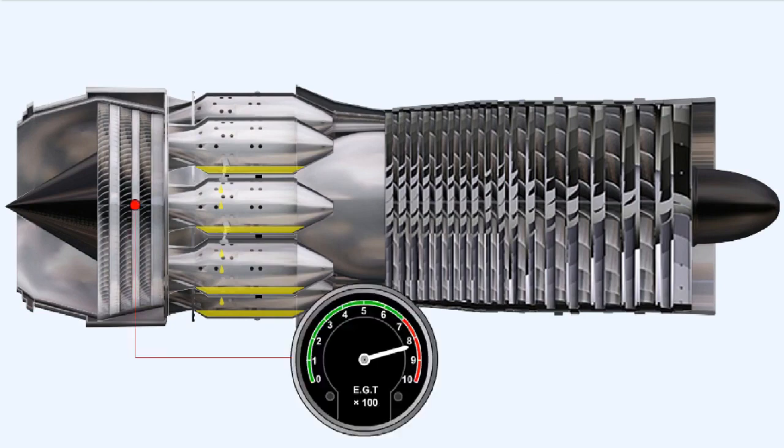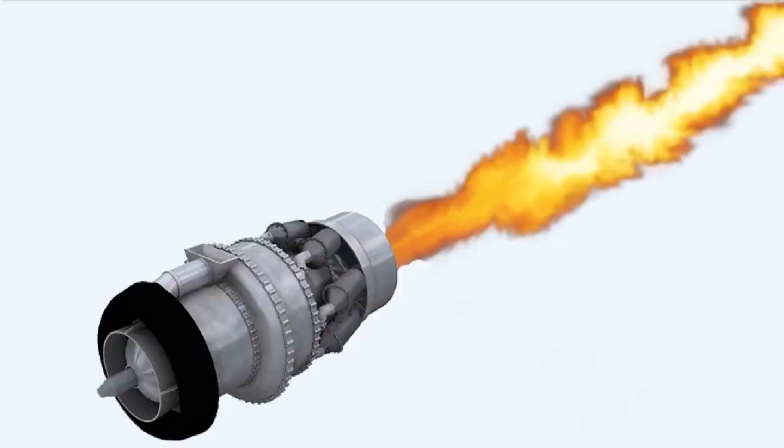If that fuel is not removed before the next attempt to start, and if that attempt is successful, the result will be a combination of excessively high gas temperatures in the turbine region and torching, which is the name for a very long, very hot and very dangerous jet of flame issuing from the rear of the engine,